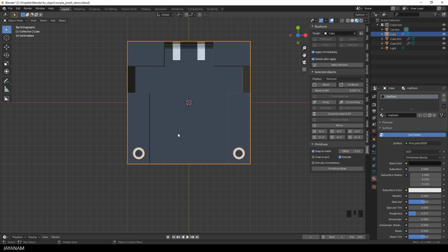And now let's add some insets here along the y-axis. Again, I use the rectangle but change the operation to difference by pressing the O key. And then I press F to draw the rectangle from the center.